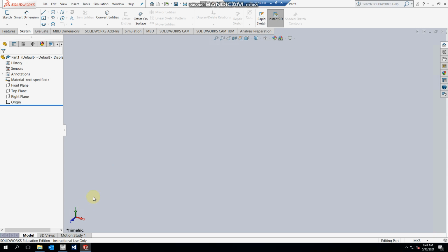But the first thing we're going to want to do is define this coordinate axis. The way AQWA reads it, the x direction is going to be the motion of the waves. So the waves are going to come from the negative x direction and go this way. Gravity is essentially negative z, so this is the up and down motion. And then this y direction, for the oscillating wave surge converter, is what it rotates around.